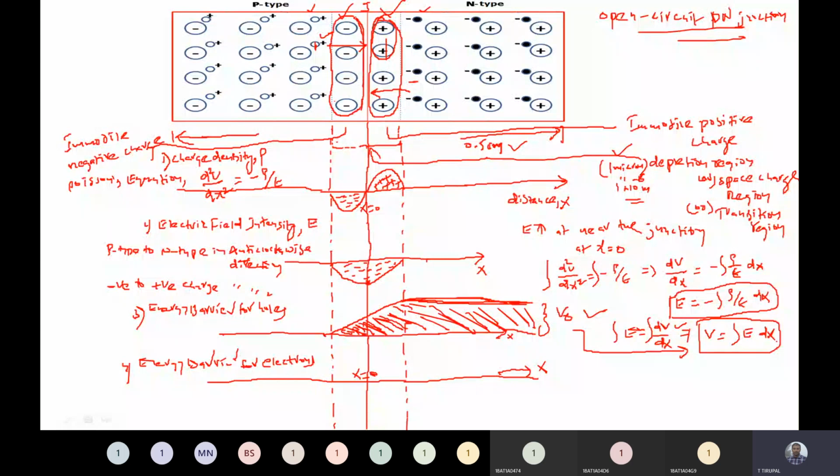A huge negative barrier is present in the depletion region which prevents electrons from crossing from n-type to p-type. So the electron has to acquire more energy externally so that it overflows through this barrier and reaches the p-type semiconductor, and in turn current flows in the device.